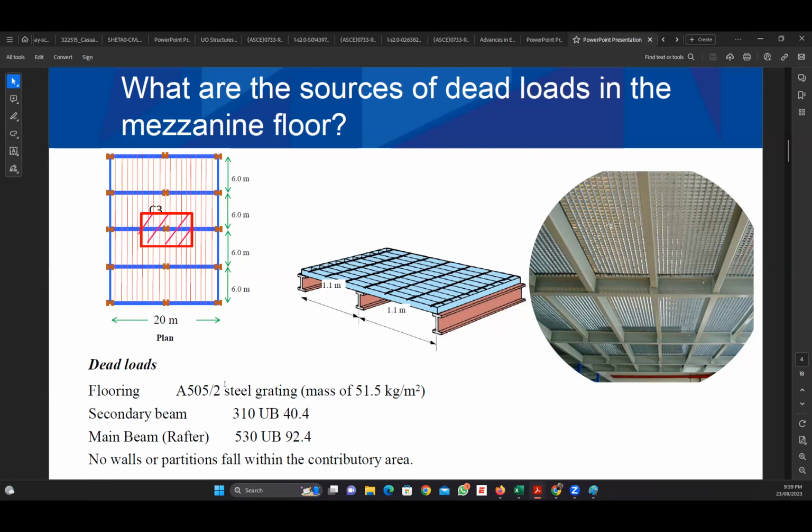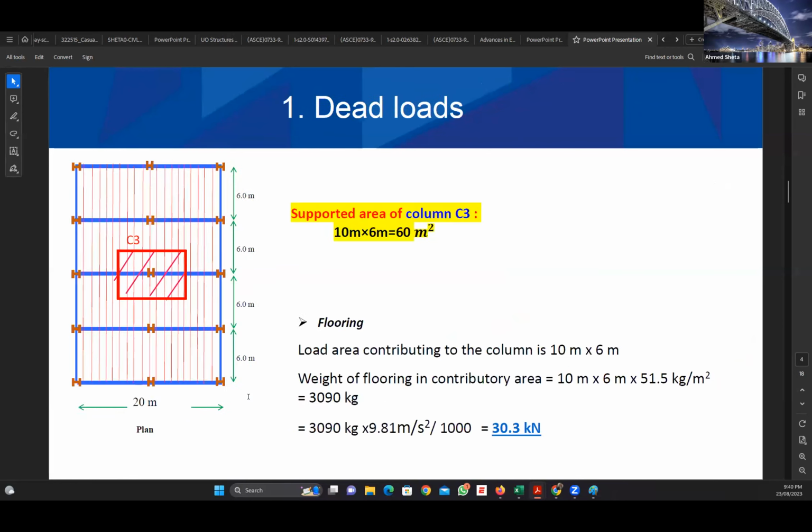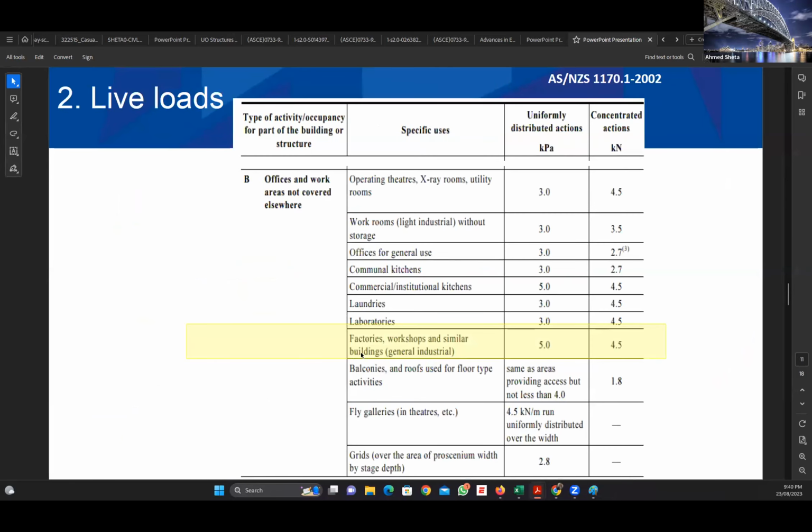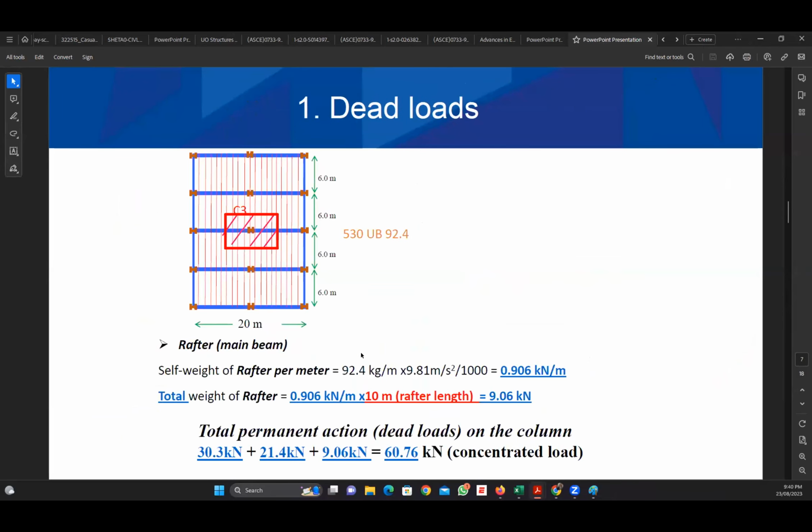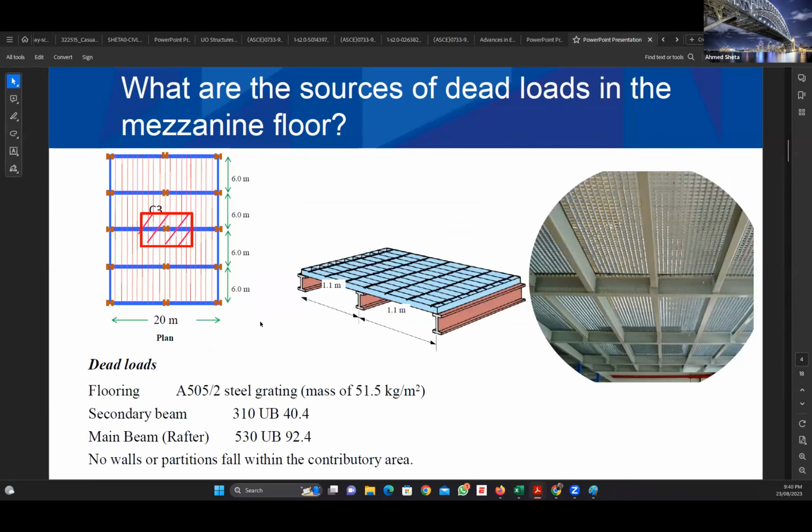Yeah, I'd appreciate that. So I want to say once again, just follow the mezzanine floor example. And instead of using the column calculations, for both the beam and the column, use the beam calculations, is what you're saying, Ahmed. Yeah, for the column, it will be the same, because nothing is different for the column. But I mean, you need to design B2. B2, for example, will be, let's say, this beam here. Can you see the mouse? Yes, I can see it. Okay, so for example, if you want to calculate the dead load, I can quickly show you something.